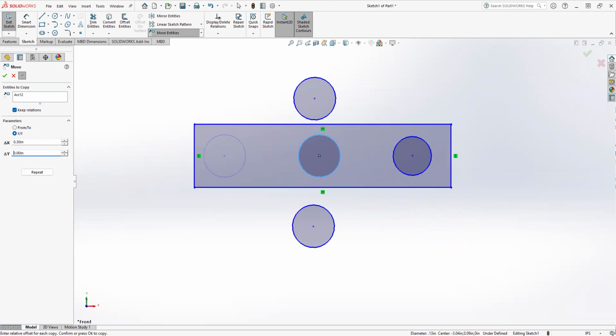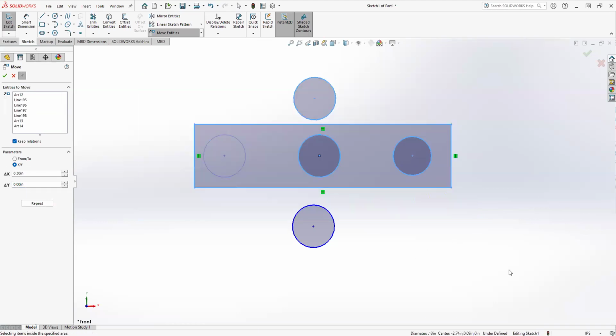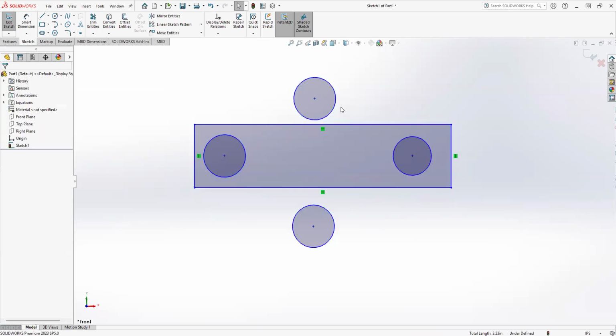Then, next one naman, the rotate entities. So, basically, si rotate entity naman, this is used to rotate an object or a group of objects about a base point. To rotate objects, you need to activate this tool and select the objects from drawing window. So, edit lang muna ulit natin. Pwedeng isang object lang i-rotate, pwedeng the whole object. Okay. Let's try.